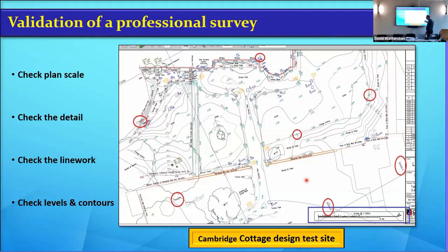The levels are related to the GPS height that I took. So that's 5.3 metres above sea level at Newlands, related to the GPS that I took, all right? So I didn't use a benchmark, I used the GPS there. I did find a benchmark across the road in St Anne's Church, and I've got a value for that from the Ordnance Survey. If I measured from here to St Anne's Church and then used the value that the Ordnance Survey gave me, it would be wrong. And you ask, why is it wrong? Because it's in a different position. They haven't got it where I've photographed it. It's somewhere else that I couldn't find.